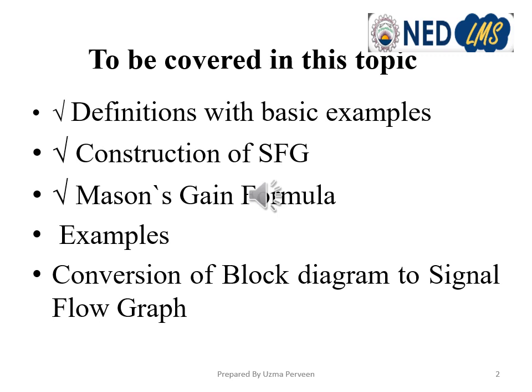And then we'll see the conversion of block diagram to signal flow graph, which is an easier method as compared to block diagram. We'll see some rules for how we convert our block diagrams to signal flow graph, and then after conversion we'll apply the same Mason's gain formula to find the control ratio or the transfer function from the signal flow graph. Obviously the transfer function obtained from the block diagram and that obtained from the signal flow graph will both be the same. So this is an alternate method to find the transfer function, that we convert our block diagrams into the signal flow graph.